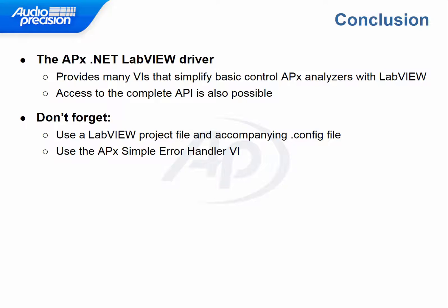And a couple of key points that I'd like to emphasize. Be sure to use a LabVIEW project file with that accompanying .config file. And also, I would encourage you to use the APx Simple Error Handler VI, because if you don't, you can get some very cryptic error messages that are quite difficult to work with. And that is the end of the presentation.